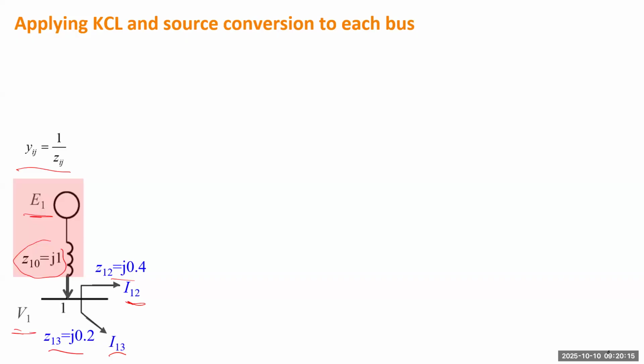So this is a pretty typical bus. For this bus, we'll find the standard model to represent it. The first step is just to apply Kirchhoff's current law, not voltage law, Kirchhoff's current law, to this bus. We study the current injection into this bus and leaving this bus.